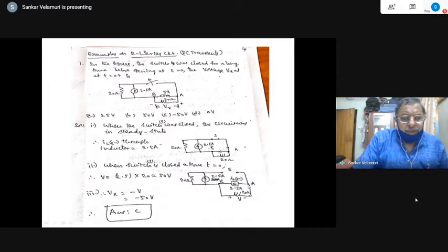Because A is to be obtained as the higher potential, B is to be obtained as this one. So in the actual direction this one is this, but this is given as an assumed one. This is given in the question as an assumed one. The actual one is computed like this. So therefore it has to be minus 50 volts. That is the meaning of this. So that is why changing the signs needs to be done carefully.